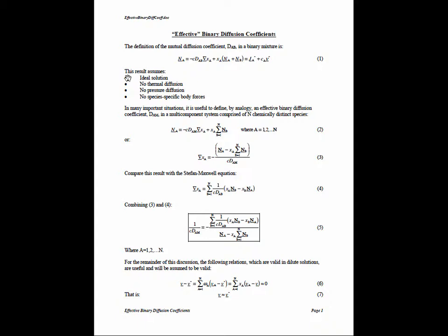And so the definition of what we call a mutual diffusion coefficient or a binary diffusion coefficient is given here in molar coordinates. That is, the flux is minus the molar concentration of the mixture times the binary diffusion coefficient times the gradient concentration of A. And the second term over here is essentially the convective or frame of reference term that accounts for all of the flux of component A that is not due simply to a concentration gradient. So this will be pressure-driven flow and any other type of convective motion.